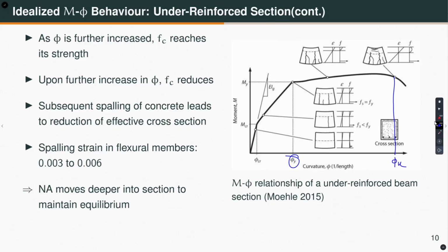Similarly, in concrete, although it is under-reinforced, eventual final failure will always be through the crushing of concrete, and you get a lot of ductility because it is under-reinforced. So, this is called the ultimate curvature and this is your yield curvature. So, the curvature ductility, which is defined by mu phi, is equal to phi u by phi y. That is the curvature ductility.